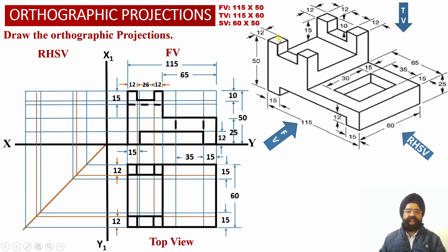So corresponding to these 4 square blocks and these 2 rectangular slots, we have been able to obtain true shape projections of each of these elements in the top view projections over here. Similarly, corresponding to this rectangular flat surface, which is the top surface of element number 2, we have been able to obtain the true shape projections in the top view projections over here.